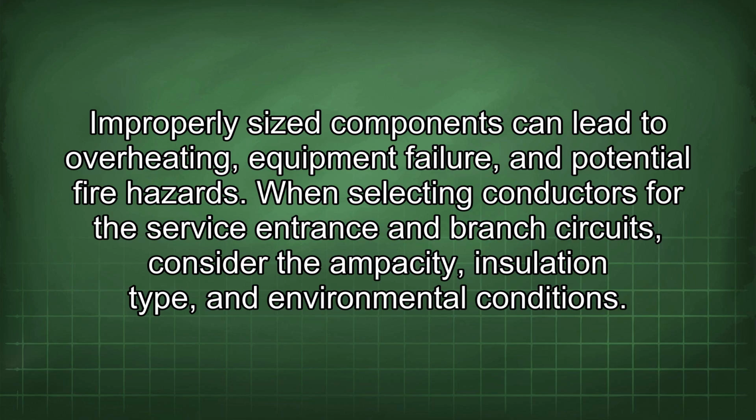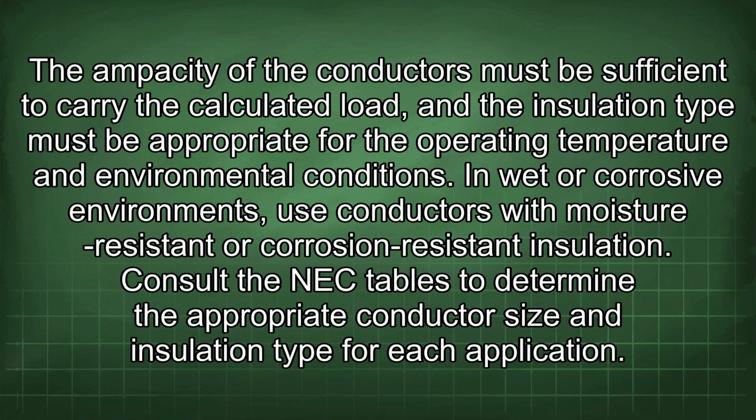When selecting conductors for the service entrance and branch circuits, consider the ampacity, insulation type, and environmental conditions. The ampacity of the conductors must be sufficient to carry the calculated load, and the insulation type must be appropriate for the operating temperature and environmental conditions. In wet or corrosive environments, use conductors with moisture-resistant or corrosion-resistant insulation. Consult the NEC tables to determine the appropriate conductor size and insulation type for each application.